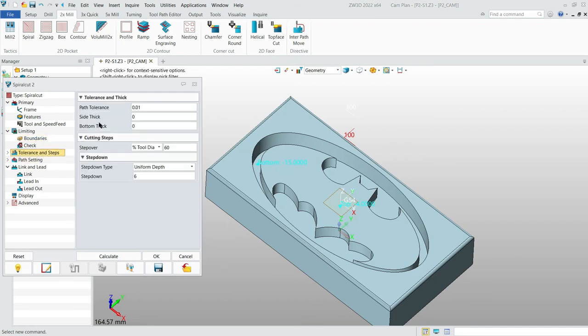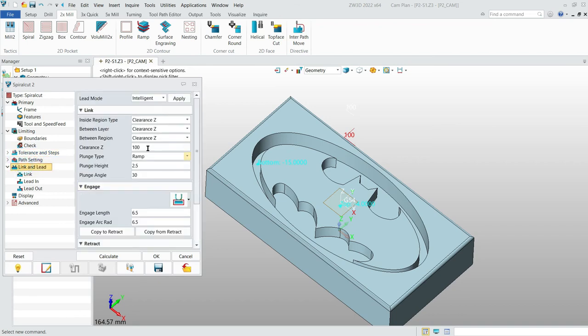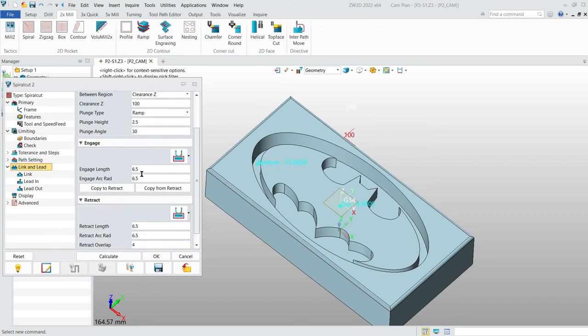So let us go through the detail. The side is going to be 0.5 balance for the final cut, as well as the bottom thickness. I have tried the 50%, that is better. So I put this as 2 for the 50% of the depth as well. So I don't want to have a finishing cut. Let me change this one. The rest I didn't do anything. So we change this one to 2. Because of limited space, let us try to do a calculate.